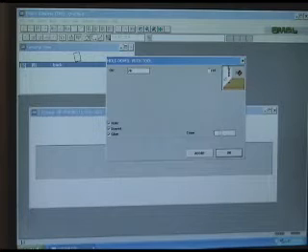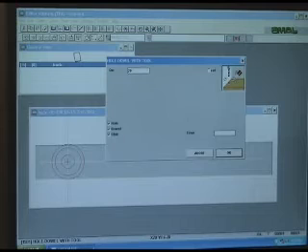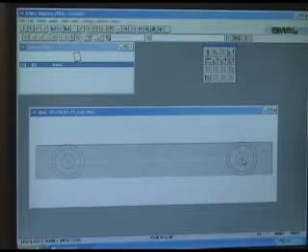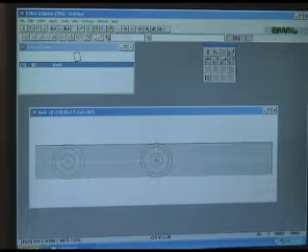And we can specify the glue time, the amount of glue that's deposited, or we can use the default. And then we'll write a new line, and using a logical statement, length minus 20, we'll put a drill and a dowel and glue on the opposite edge. Just making a rail, we can also specify length divided by 2 and put a drill and dowel in the center of the panel.